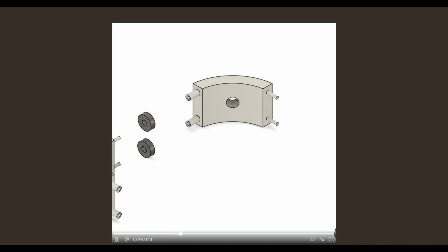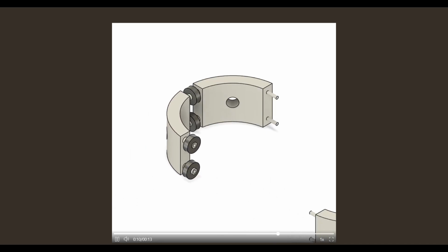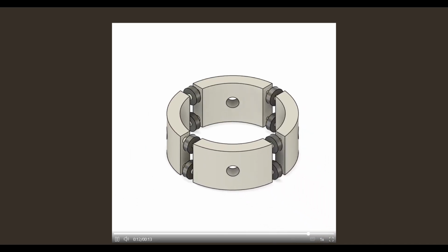This video is a demonstration of the process of assembling the collar out of the 4 pieces. Clearly you can see how it's as simple as aligning the pins of 1 quarter to the slots in another, and the 2 are held together neatly by the frictional force. The ball bearings should be put on before connecting the pieces. They are also held tightly on the slot part of the other joint.